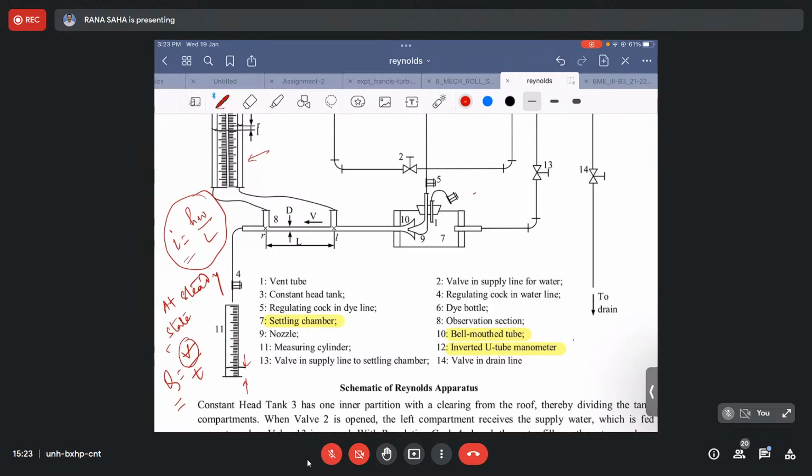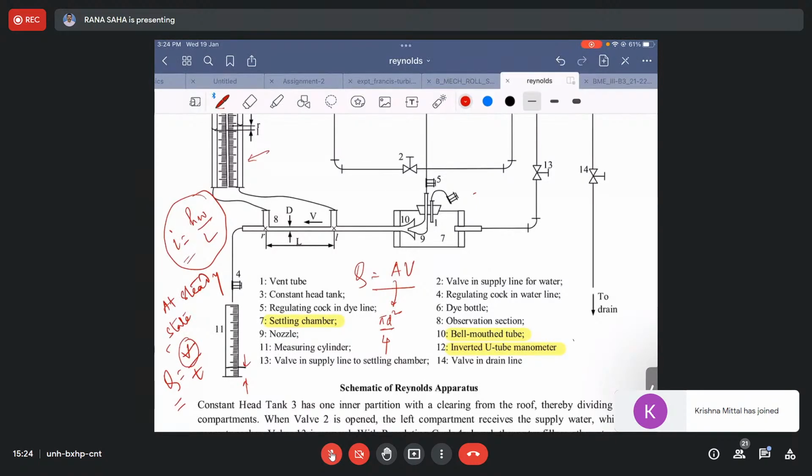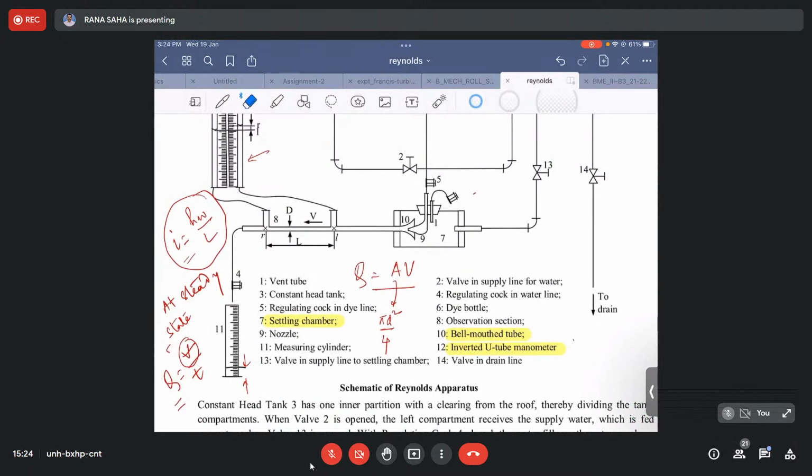But our point of interest is not exactly the flow rate, but the average velocity v. So for steady state, now you need to use the steady state continuity equation in integral form. That means we can write Q is equal to AV, right? This is our steady state relation of the continuity equation, correct? Where this A is the cross section of the pipe, which is pi d square. Here, inconsistent with the notation used, it is actually pi capital D square by 4, right?